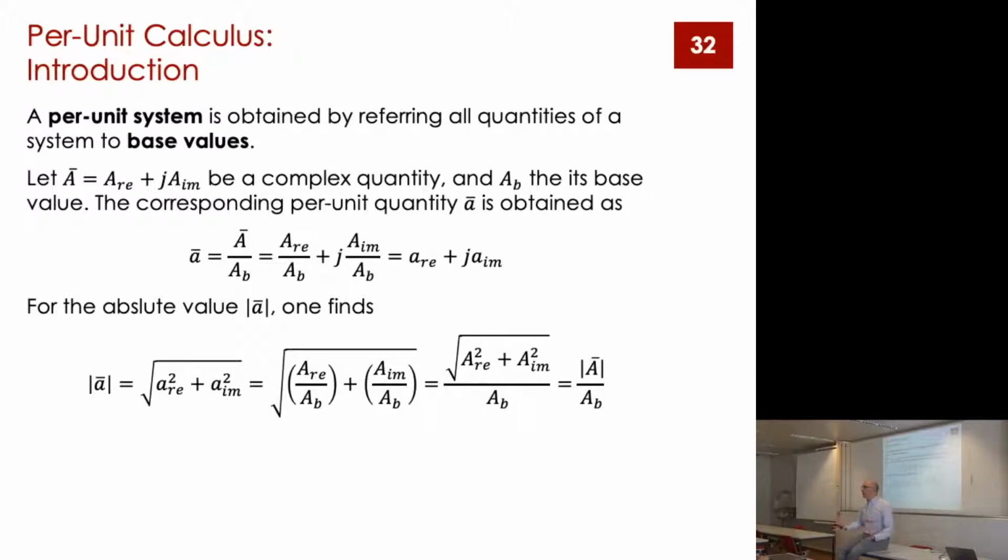Even in a power grid, you can have flows or injections which are in the range of gigawatt, so 10 to the plus 9, and current flows which are in the range of amps. So you have quantities which are moving over several orders of magnitude. Now, when we put these numbers into a numerical solver, we are using computers, and computers don't have infinite precision.